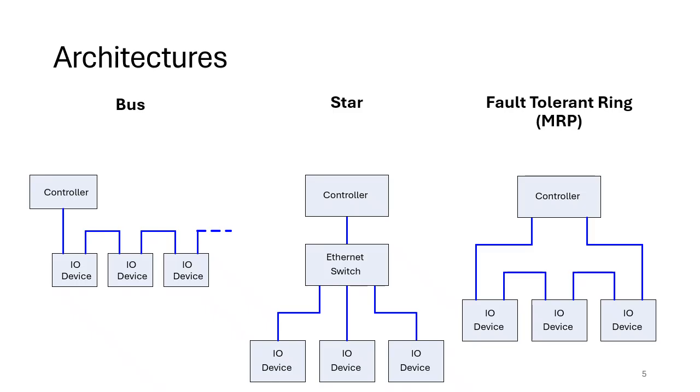Also, we talk about it handling a single failure, but you could get multiple failures and the system will still degrade gracefully. So for example, we've got 3 I/O devices here. If the first and second I/O devices fail, we've got 2 failures, but it will be fault tolerant to some extent because the third device will still continue to work. So in order to determine what the effects are, you do some sort of failure mode effect analysis to work out what happens, and then that can aid you in deciding what your network architecture should look like and how many devices you need and so on.